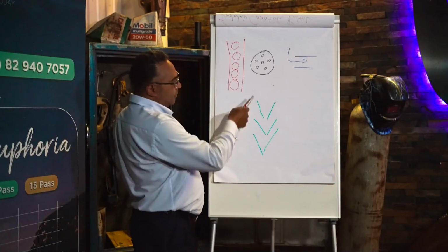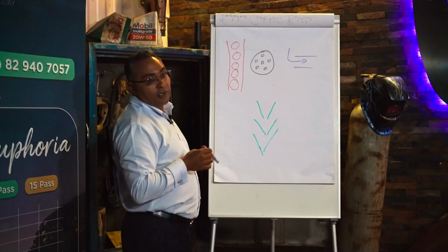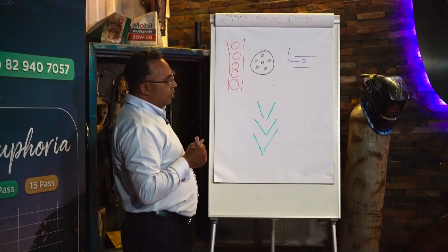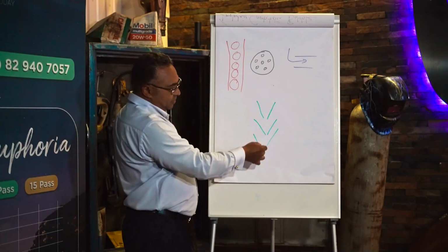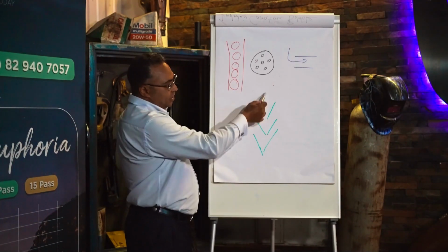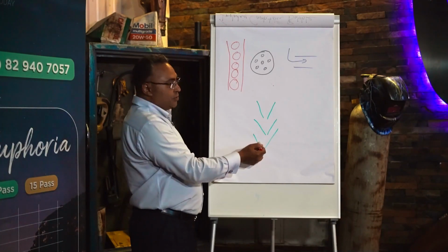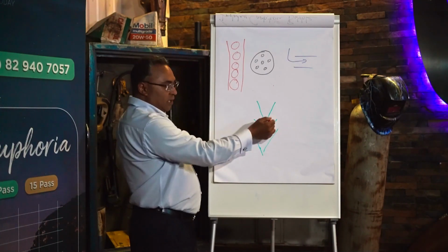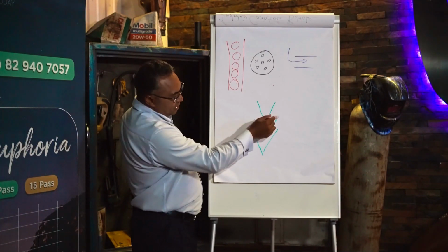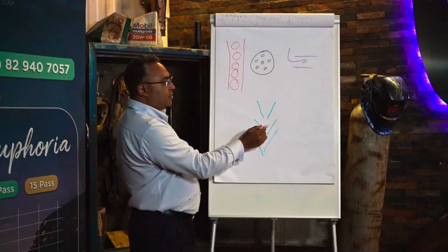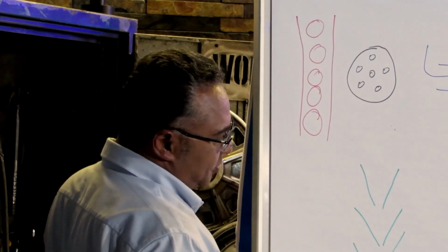Now the MACH is working in complete harmony with nature, as opposed to all of the other historical methods. And how we do that is through a process of cavitation. So we're pumping slurry through a system of venturis. And as we accelerate the pulp through the venturi, we create this suction effect between the venturis. So we actually suck in the gas, we pull in the gas. And then between the two venturis, as the one venturi is jetting into the other venturi, we create these areas of extreme turbulence and mixing that helps us disperse the pulp.